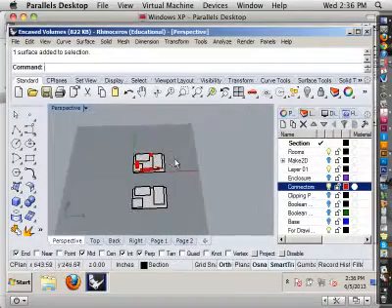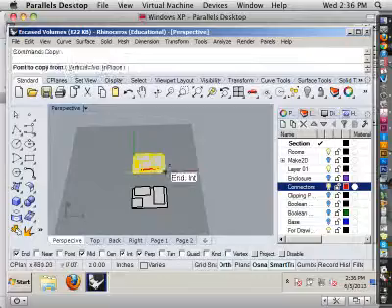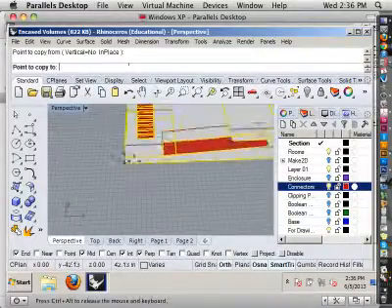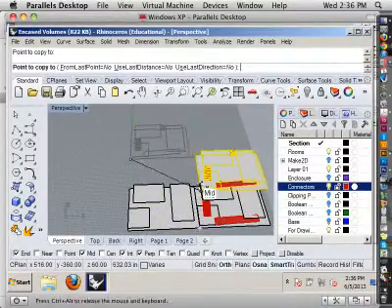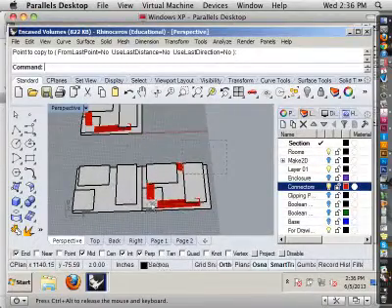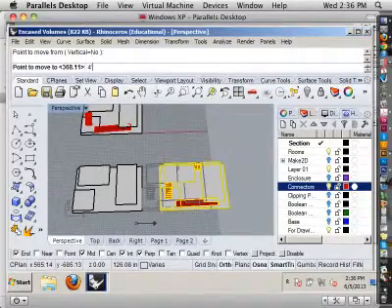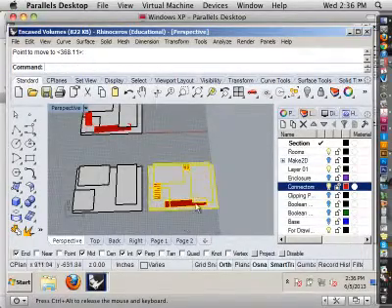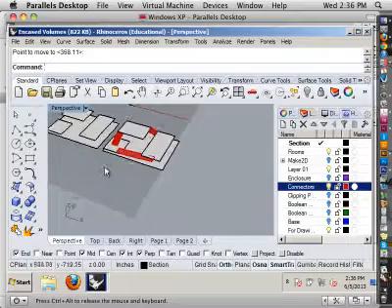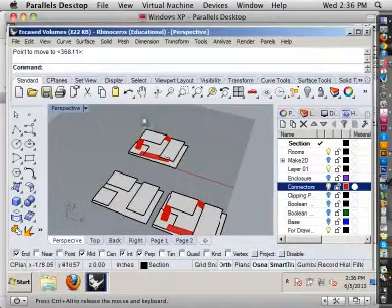Okay, when you've got it to that point, I'm going to make a copy, and I'm going to copy it from this corner point to this corner point, and end the copy command by right-clicking, hitting Enter or spacebar, and then taking these and moving them 4 feet to the right, which is our set distance. Right, so I'm starting to set up the sequence of things down here without dramatically modifying this original, so I can turn things on and off. Everybody still with me?